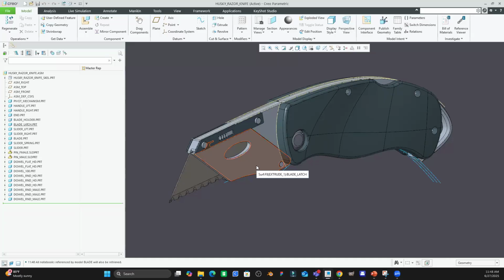So the engine's very similar across the board, but maybe there's just subtle things about the engine that are different, right? Well, what's cool is that you can create an interchange assembly so that you can swap out the different versions for each other without having to redefine the constraints when assembling them. All right. So this is pretty cool.